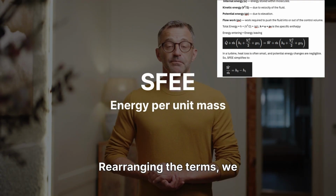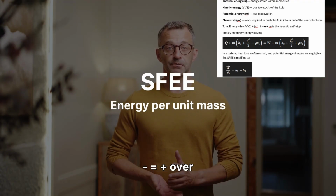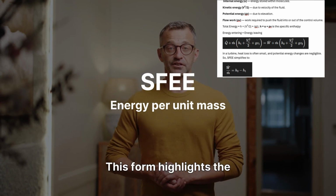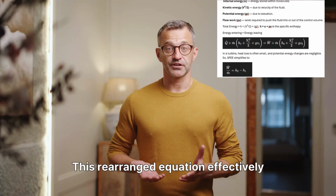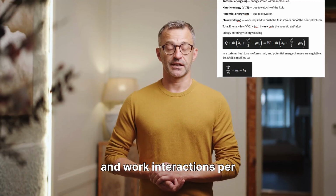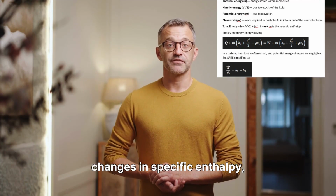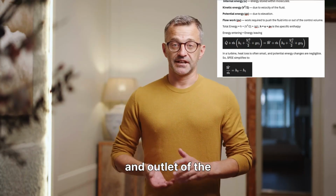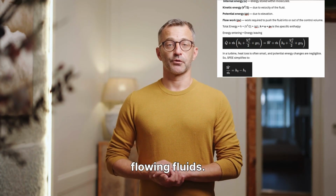Rearranging the terms, we arrive at the SFE in its most practical and commonly used form: q minus w equals the change in h, plus the change in V squared over 2, plus g times the change in z. This form highlights the changes in energy per unit mass. This rearranged equation effectively relates the net heat and work interactions per unit mass to the changes in specific enthalpy, kinetic energy, and potential energy between the inlet and outlet of the system. It acts as an energy accounting system for flowing fluids.